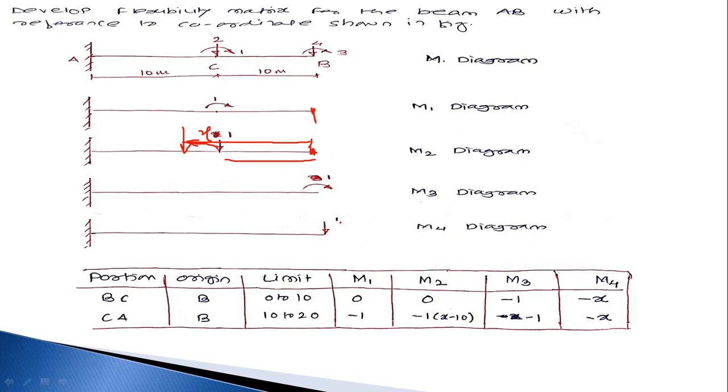Then next, at coordinate number 4, that is point load at point B, X measures from point B. So this is directly 1 into, suppose this is the load moving towards A. So it becomes similar to that point load, that is 1 into X, and the direction of the moment is anti-clockwise, right side and left side anti-clockwise, that is minus 1 into X. So it becomes minus X.